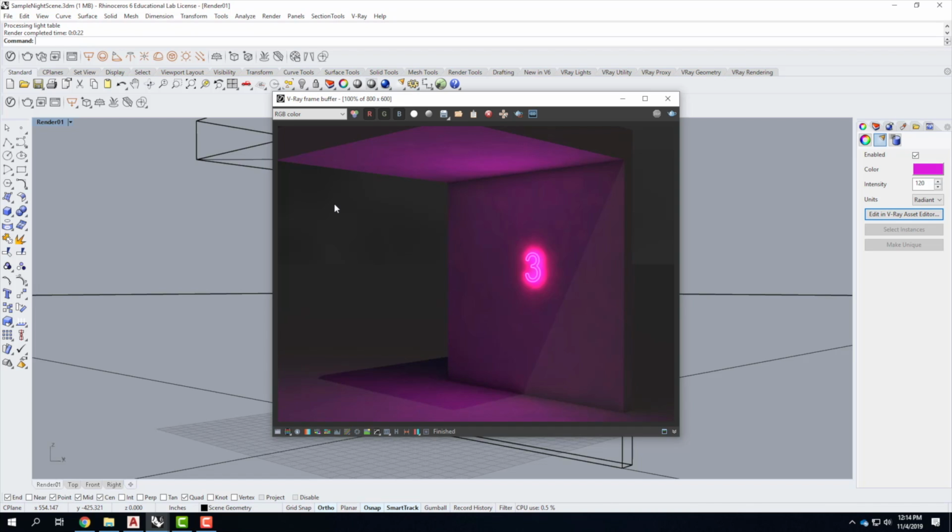It's really important for you guys to know that when you save your Rhino file and you bring it in as a block into another file, if you put a V-Ray light into the block, the V-Ray light will not transfer through with you. So your V-Ray light is always put in the final scene that you're doing your rendering. So on your retreat, for example, that scene with the background and everything that we've been doing our renderings from, that's where the V-Ray lights will end up. They won't end up in the blocks. So they always end up at the final stage of the renderings.